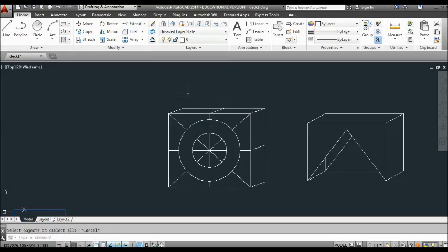But before I do my extend command, I'm going to make this guy a little bit thicker first. So I'm just going to use the copy command, and I'm going to copy this back line, and I'm just going to put it in as an angle 20, enter, and it's asking me for my second point, so I can either just simply drag it because it's keeping it on my 20-degree angle, and we'll just make it that big, and enter.